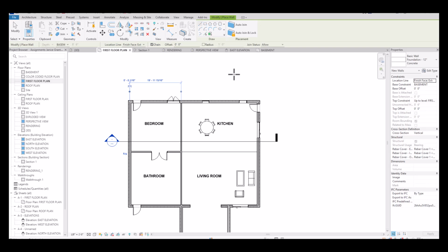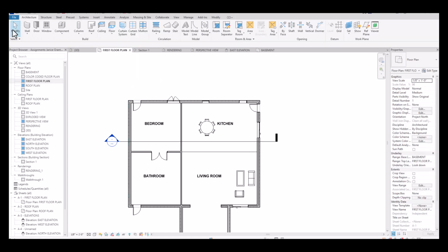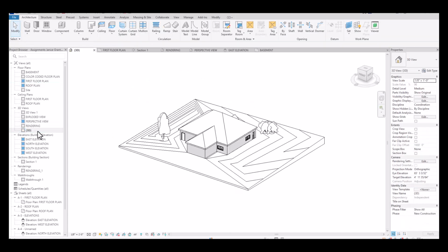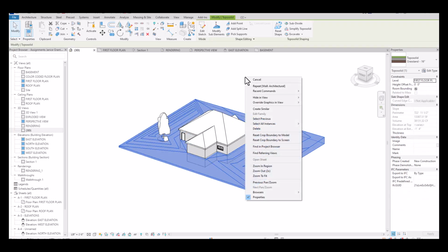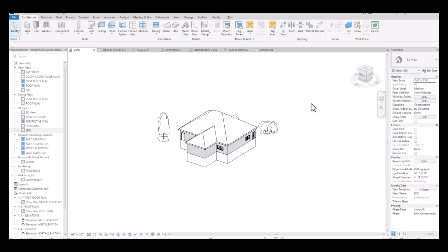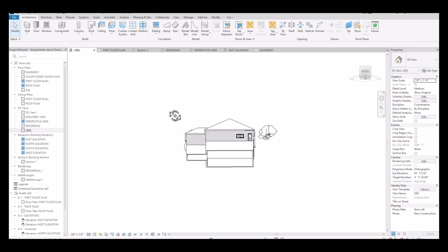Now that I drew all of those, you can't really see them, but it won't give you a default because we changed the overlay so that we're looking down to the basement. I am going to now show you this in the 3D view. In the 3D view, we can turn off the solar panels that we had in the shadows. And actually, I'm going to temporarily click on the site, right click, and hide in view category. These are all going into that dialog box that is VG, typing in VG. So there it is. There's my foundation.